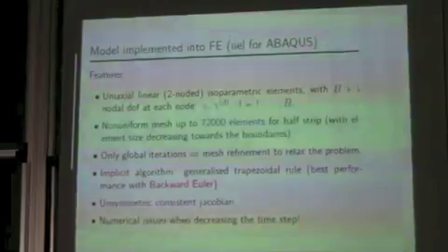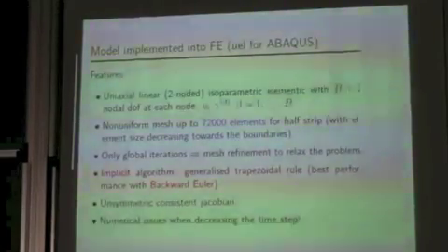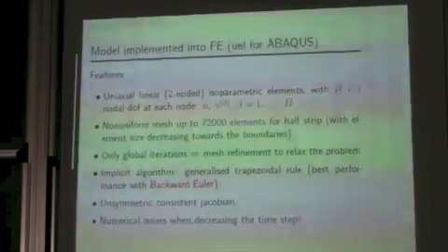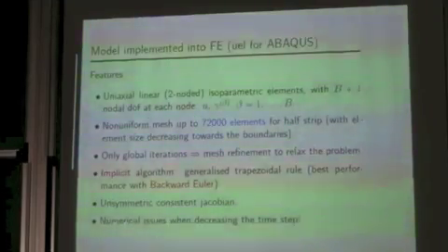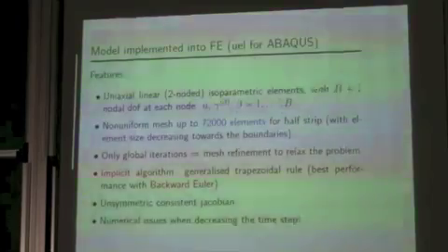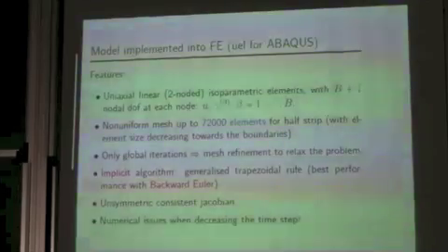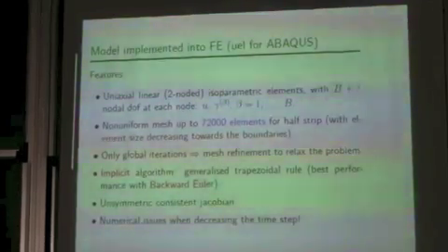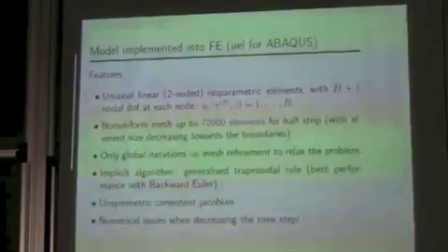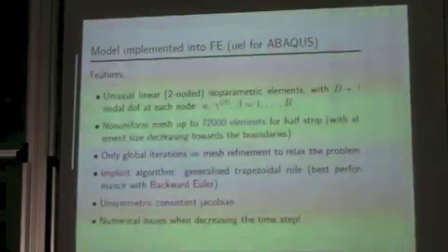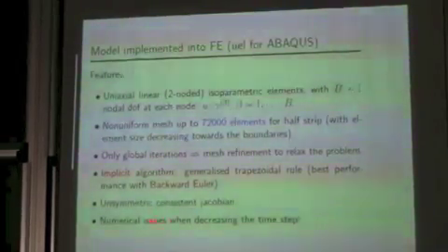So in order to allow convergence, you have to increase the mesh. You cannot put many other ingredients in the algorithm if you have no access to the global iteration scheme. And this is the case, because I had the bad idea to use Abaqus, and I have no access to the solving of the system.